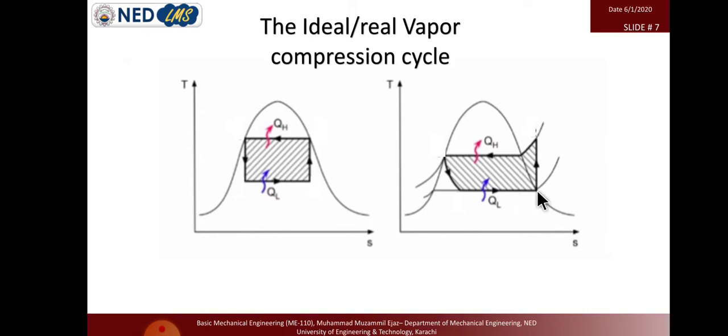So we have to move this liquid towards the saturated vapor, and when it has completely evaporated, the gaseous refrigerant goes into the compressor, and then the compressor compresses the gas, due to which the gas becomes superheated. It is not water, so even in the superheated state, the temperature is like 70 or 80 degrees centigrade, not like water, more than 100.